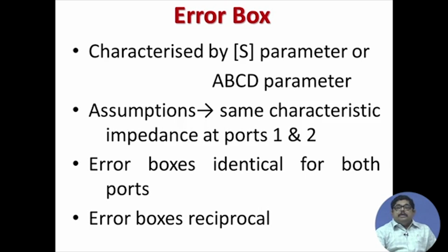there are assumptions made, but if the assumptions are not valid, you can always rework that. At the two ports, whatever extra thing you connect, those error causing connectors, etc., are symmetric and have the same characteristic impedance. Now, if not, you know how to handle different characteristic impedance; in the generalized S parameter, we have shown you that.